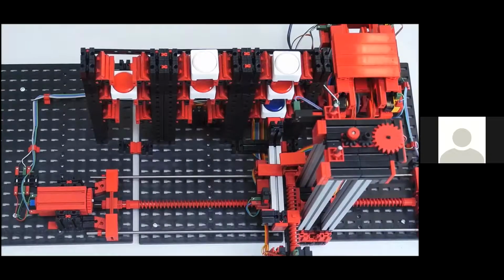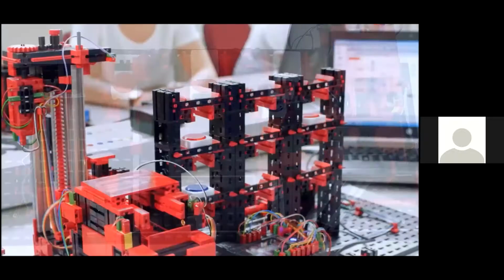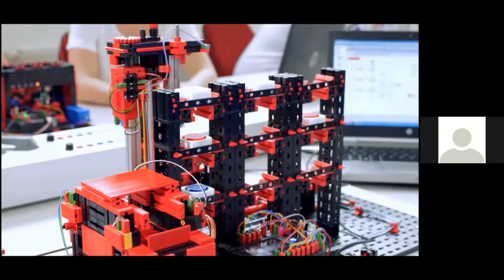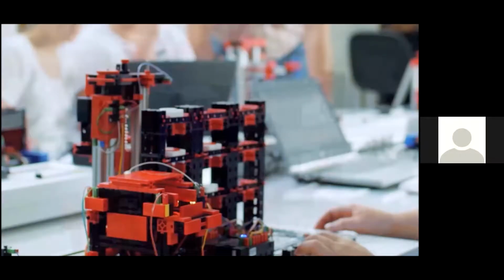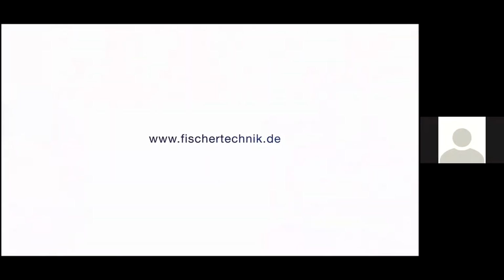Again, the 24-volt version has a relay board for motor polarity reversal and both a multi-pin connector, 34 pins with a grid of 2.54 millimeters, as well as additional PCB terminals with push-in connections for all inputs and outputs. Again, you will need to provide your own PLC and programming. And for a limited time, a 9-volt version is also available, which is pre-wired again to the pre-programmed TXT controller, and one 120-volt power adapter is required for that.